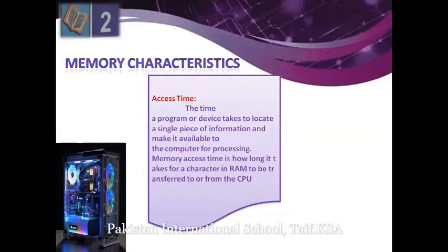So it is the time taken to retrieve your data from memory. If you want to retrieve your instruction from random access memory and from sequential access memory, it depends on the time taken to access your instruction. This is called the access time. The time taken in sequential access devices is more than in random access devices. So you can access your data quickly in the random access method, and in the sequential access method, the time taken is more.